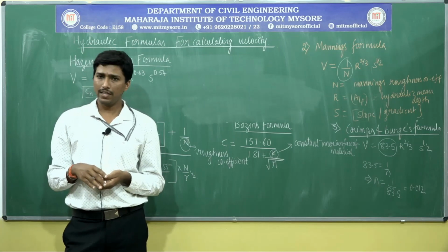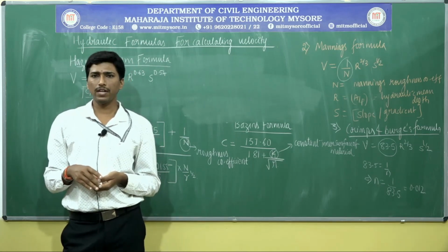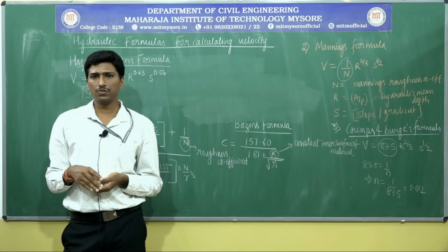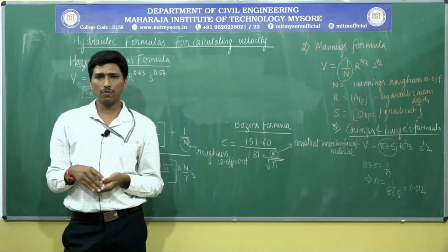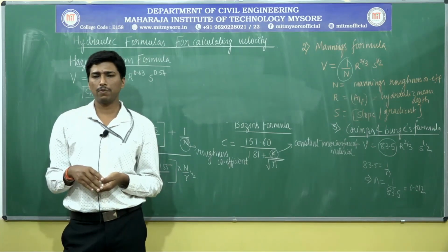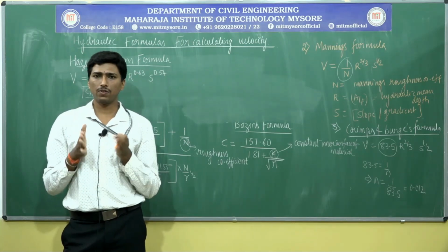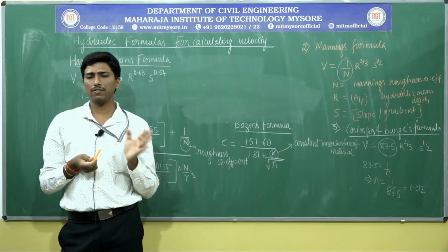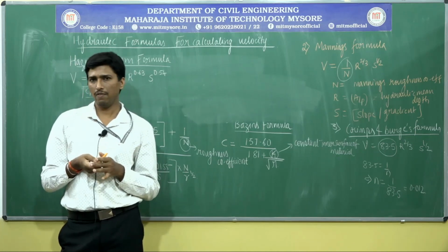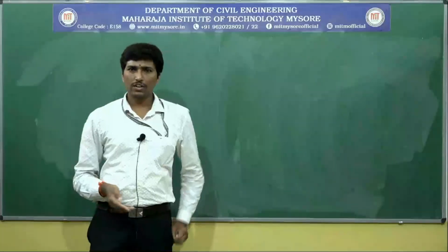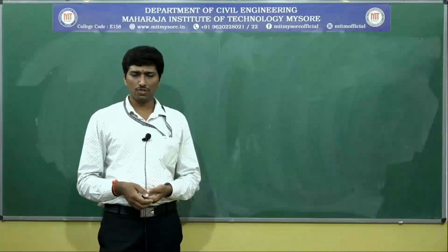There the plastic pipe surface is quite smooth in nature, therefore the velocity of flow can be established at the maximum rate, and that is the reason we come across fixing the values for the minimum as well as the maximum velocity. Now we shall continue in the next part of the session. Thank you one and all.